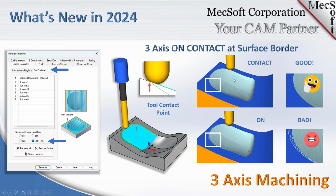So if you look in these simulations, you'll see that down below in previous versions, the tool was riding up on the parting line and actually messing up the parting line. And you would see that in your actual molded parts, which is not good.